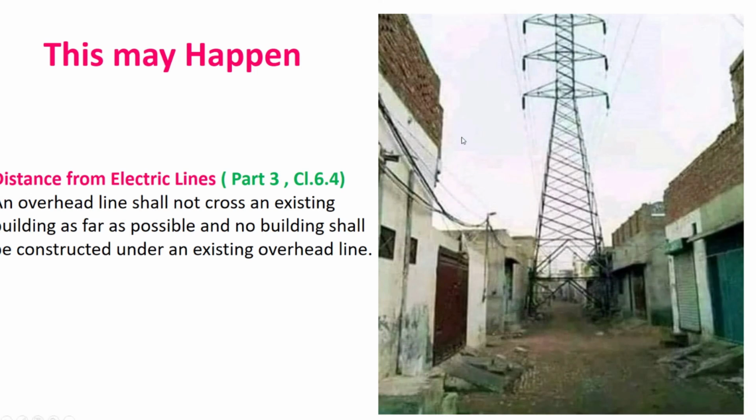In case of a clayey soil, penetration below the zone where shrinkage and swelling due to seasonal weather changes are there, I need to go below that, due to the trees or shrubs which are likely to cause appreciable movement. You may be having trees, having roots. Then if the roots are at 3 meters, then possibly you will be required to go further below.